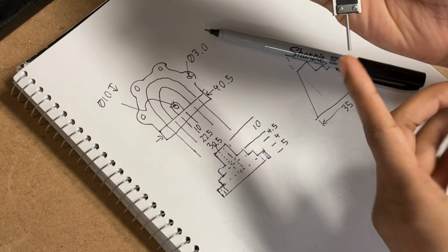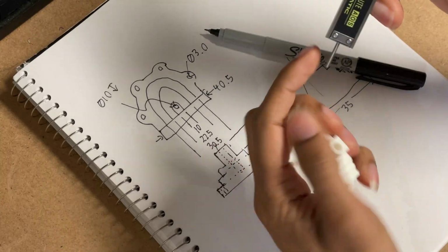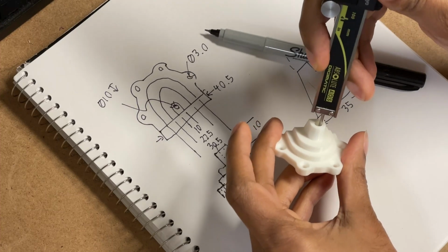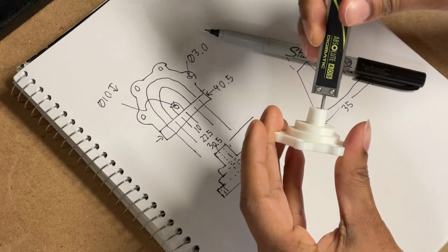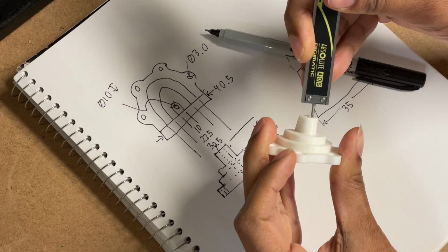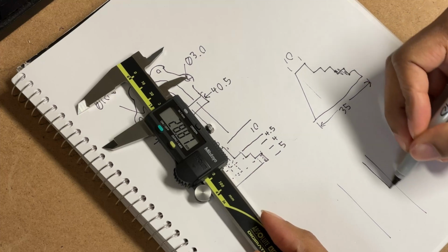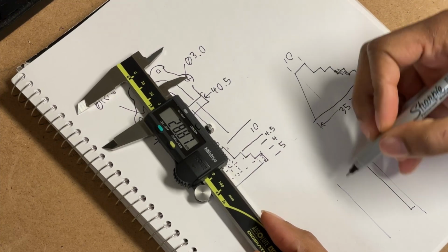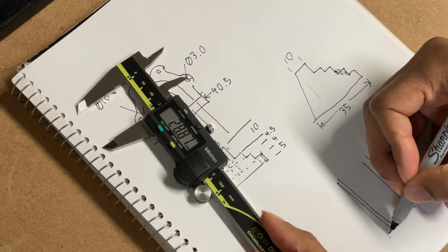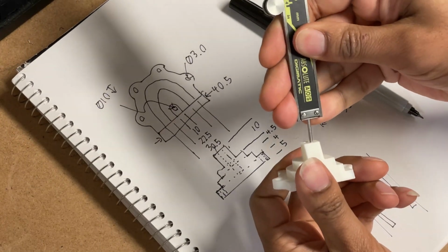Okay, there. What was happening was this edge here was getting caught on some of the layer lines. Because what I'm trying to do is run this cylinder down the side of the part, but you can see how it's kind of getting stuck. Anyway, take the measure. And the reason is, if I run it down the side of the part, then I know it's, let me just draw it out. So here's our hole. If I run the cylinder down this side wall, then I know that it's square on the side wall. What I don't want is the cylinder to be like this, at some angle and a gap there. I'm trying to be parallel with the walls. So here we go, let's take this measurement.